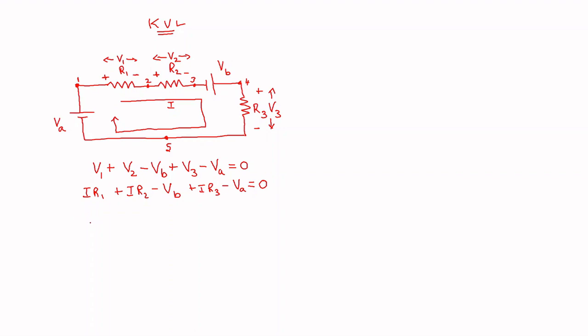Students can use an alternate way of writing the same equation, that is by using sum of voltage drops. This is the other way of stating Kirchhoff's voltage law, that is sum of voltage drops in a closed loop is equal to sum of voltage rises. To do this, we should identify among the 5 potentials which come under drop and which come under rise.